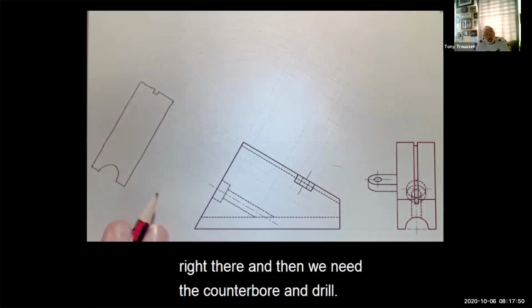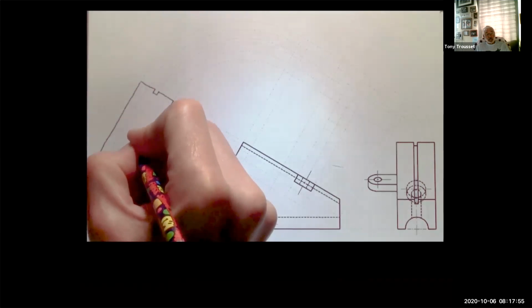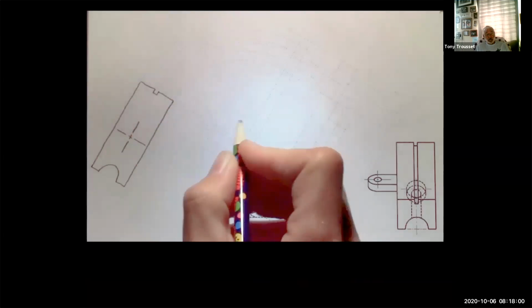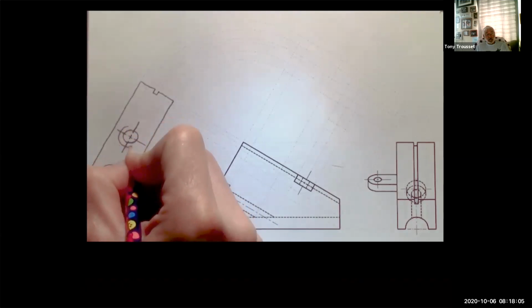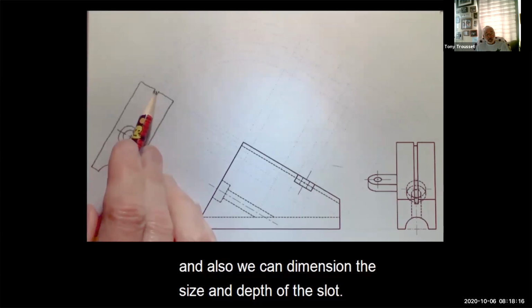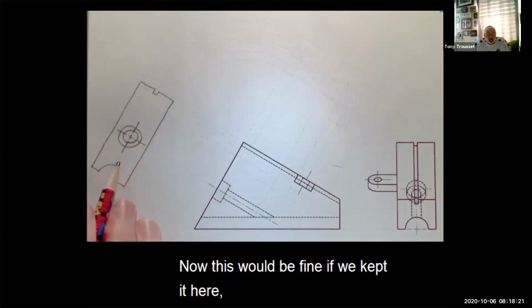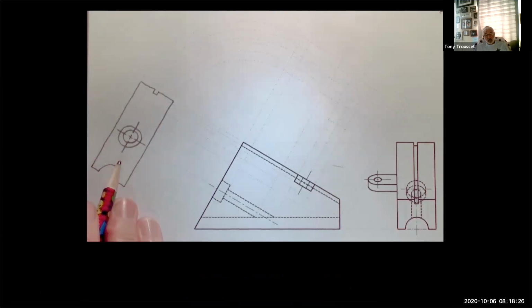right there, and then we need the counter bore and drill. And that's going to go right here. And that's really the reason we need this view, so that we can dimension this counter bore and drill. And also we can dimension the size and depth of the slot. Now this would be fine if we kept it here, but let's go ahead and do the complete auxiliary view.